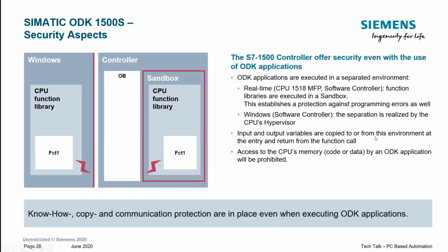With regards to security, it's very important to note that these ODK functions, although they live inside the virtual machine for the controller, are completely sandboxed. So if there's any badly written code or even malicious code, there is no way that it can leak out and cause havoc within the controller itself. It's completely executed inside a sandboxed environment. And again, on the Windows side, having those two virtual machines is just security by design. What is running in Windows can't harm what is running inside the software controller itself.